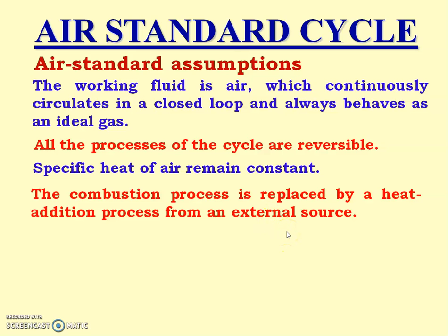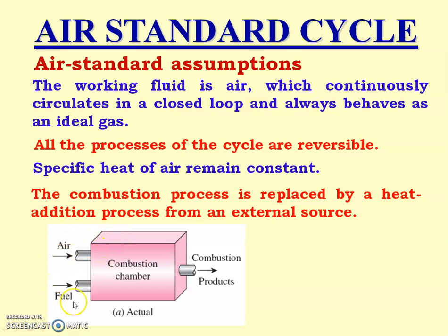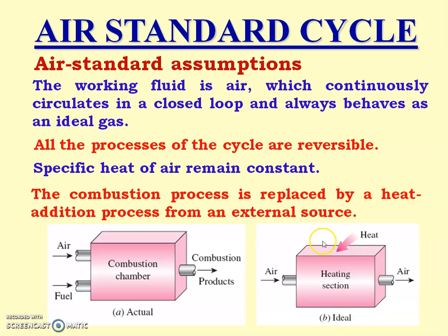Now let us see what is combustion process. In a combustion process, air and fuel enter, and in presence of air, fuel burns and energy is generated, and the combustion products now enter or work in the engine. That is known as the combustion process. But for air standard assumptions, this combustion process is replaced by heat addition. Now what is heat addition? Only air enters into the heating section and heat is supplied from the outside, and heated air now works in the engine. So that is known as the heat addition process, and that is one of the assumptions in air standard cycle.